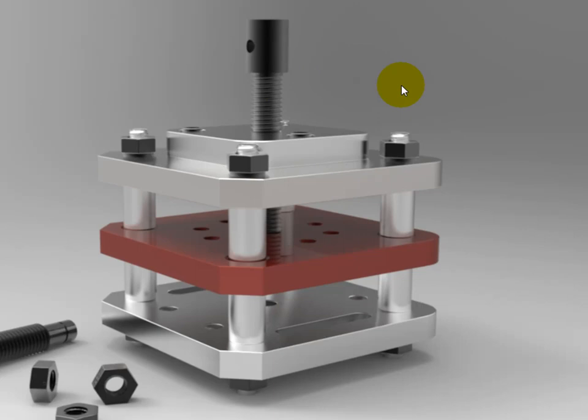You'll be able to see that the 3 plates are very similar, just they all have different holes through the centers of them. So what we're going to do is model one plate and then do a save as, and we'll save it as base plate, middle plate and top plate. We will then make the corner posts, which are named part 6, and also the main shaft, which is named part 7.